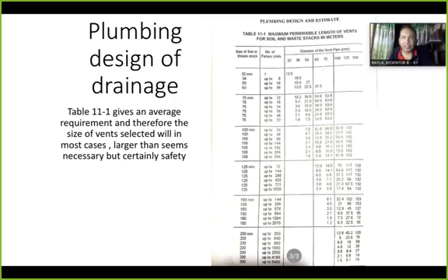So that is venting. So we have the diameter of vent pipe, we have the number of fixtures. We have the diameter of pipe, we have the size of soil, the waste stack here. We have up to 200 mm or 8 inches. We have the fixture unit up to 5,400 fixture unit.